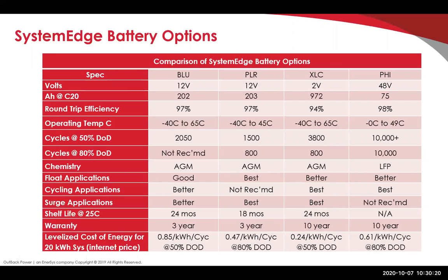One thing I want to chime in, we got a question that said, to achieve the UL 9540 requirement, does the energy storage have to be a lithium chemistry? And if that's true, wouldn't AGM be ruled out? Yeah, this is a really good question that you asked. I'll try and clarify it as best I can. UL 9540 only applies to lithium batteries, okay?